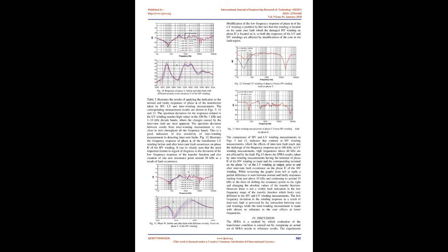In order to prove the characteristic signatures attained for inter-turn faults, inferred based on the inspection of the transfer function of the winding in faulty and normal operating conditions, additional experiments were performed with different levels of fault severity in the shorted turns.